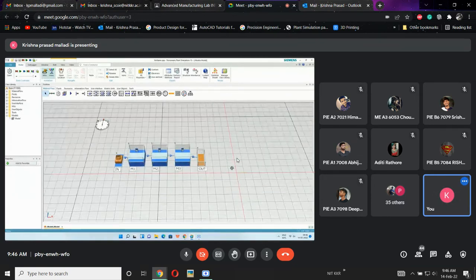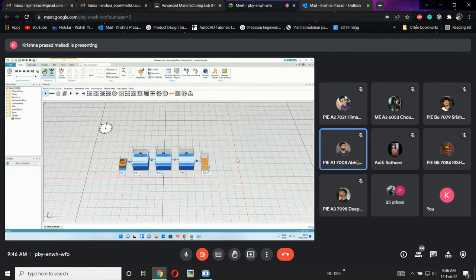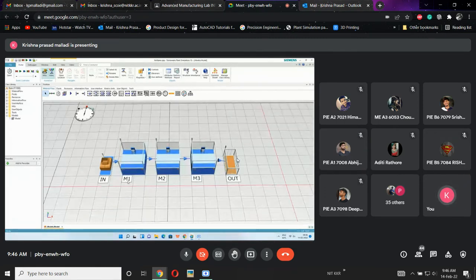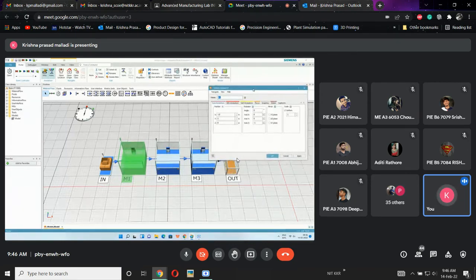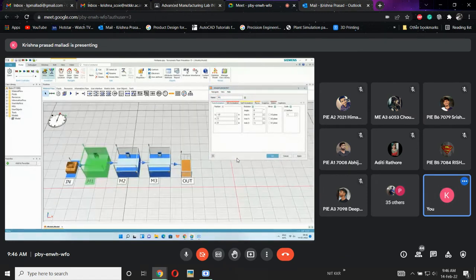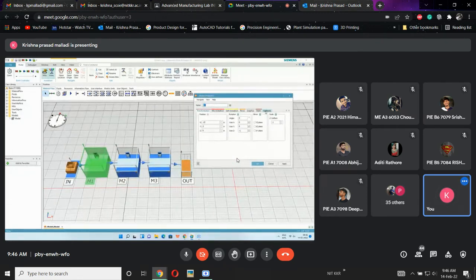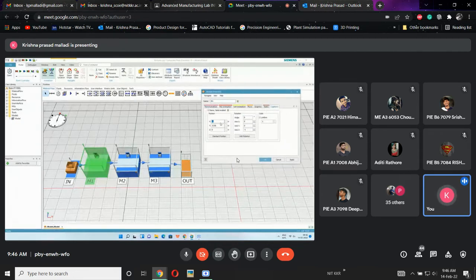Okay. Now, this is the first thing. Clear? Yes, sir. Now, one more thing here. See, I don't want this M1 at this location. Instead, I want this M1 at this corner, instead of this starting point: M1 at this end, M2 at this one, M3 at this position. Then right click, edit 3D properties, and you have to change that in the captions tab only. In the captions tab, it is written here: -1, -0.5, Z 0. You can alter it. Instead of -1, I am pressing 0.